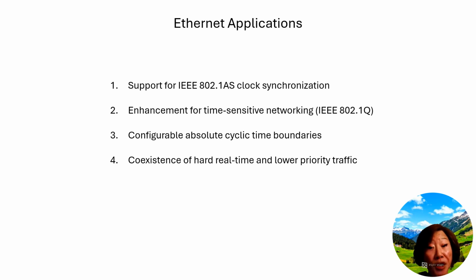This involves precise coordination between the 5G system clock and the TSN domain clock, often achieved through techniques like Generalized Precision Time Protocol, gPTP.